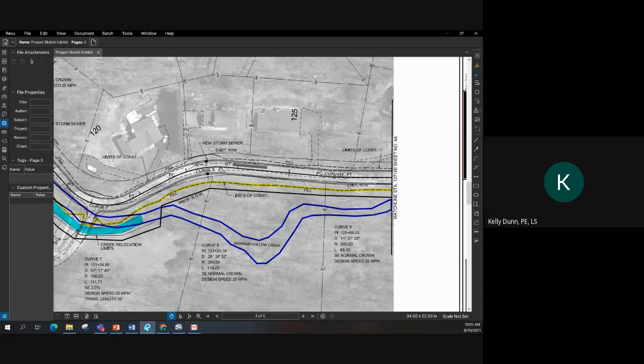Anyways, that would require more inlets and associated piping to capture all that. And so what I'm getting at is, probably on this side of the roadway, you're going to have a lot more curb inlets, and they're just going to be flanked. They're going to be down this way every couple of 100 feet to capture all this runoff. On this side, something like what's shown might be adequate to pick up the little bit of runoff that you're going to have in here.